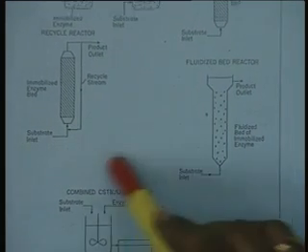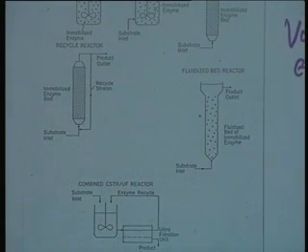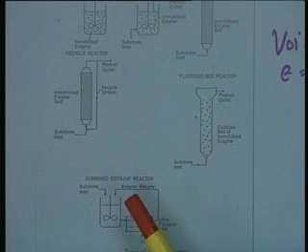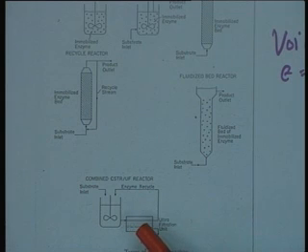And in another case, if you look at the combined CSTR and ultrafiltration reactor, which is one of the model systems which has been used for substrates which are solid in nature, and where the enzyme is required to be used in soluble form. One can carry out the reaction in a stirred reactor, in a CSTR, with the possibility of the product stream passing through an ultrafiltration chamber, whereby the enzyme is recycled back and the product is withdrawn from the permeate stream.